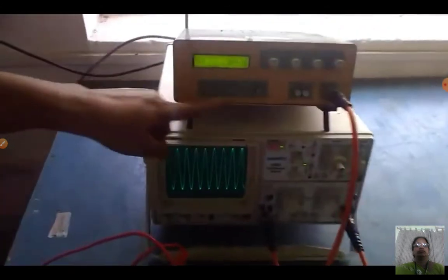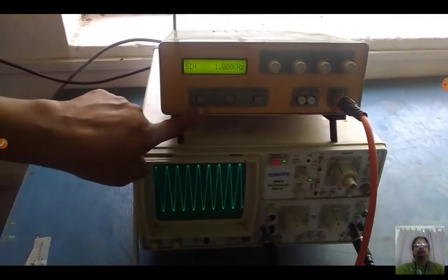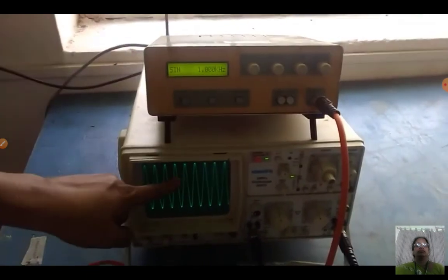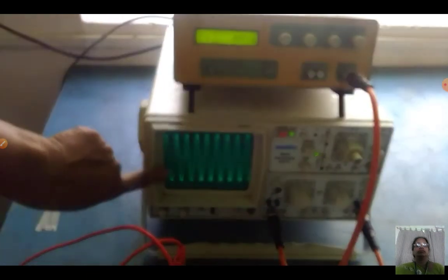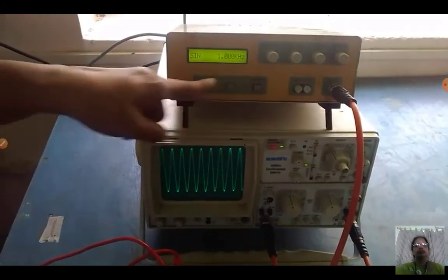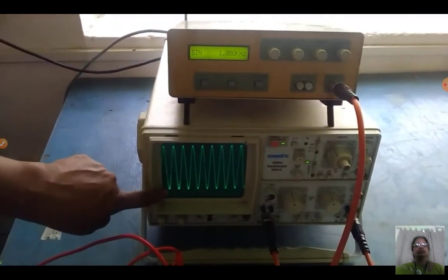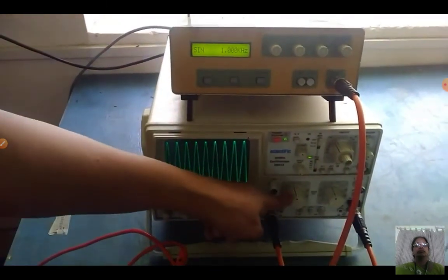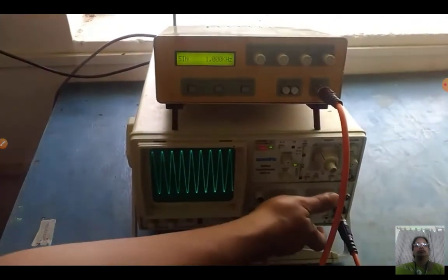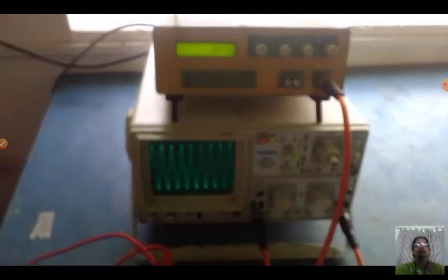Using the waveform button I select the sine wave. Using the range button I select 1 kilohertz. I have to set the peak to peak input voltage to 3 volts using the amplitude knob. Here we see 1, 2, 3, 4, 5 divisions multiplied by 0.5 volt, so we are getting a 3 volt input. The output I also put in channel mode 2, and this is also 6 volts only output.